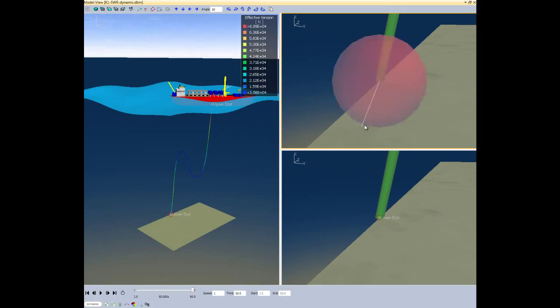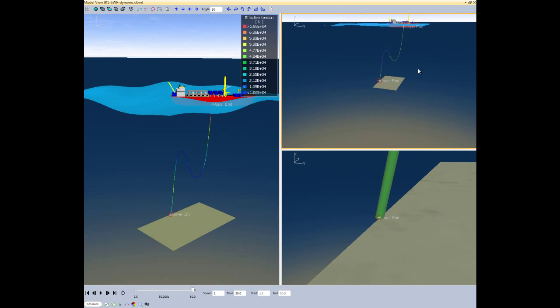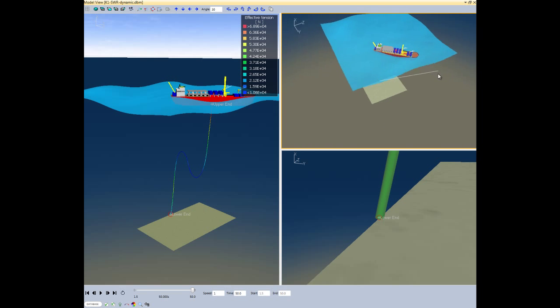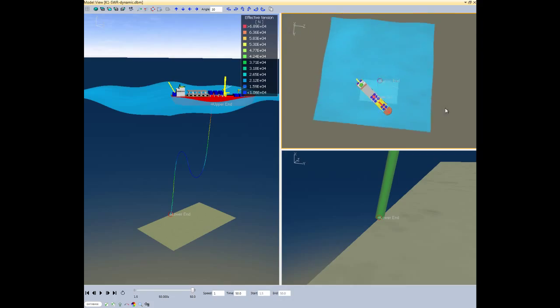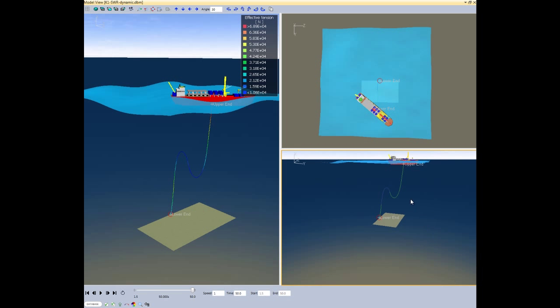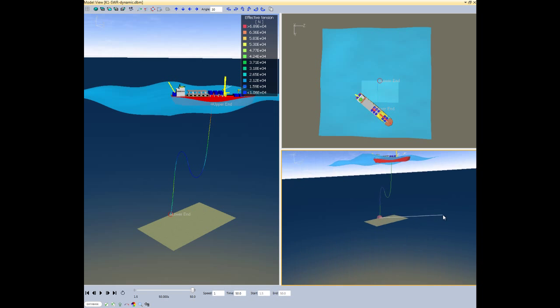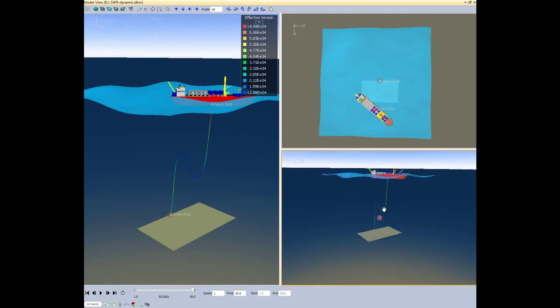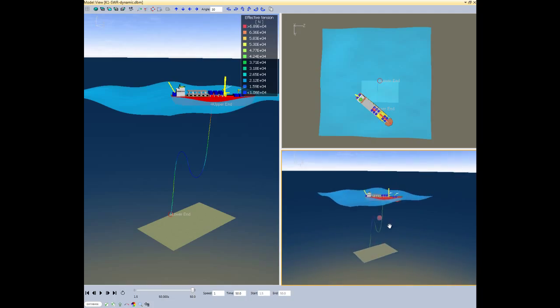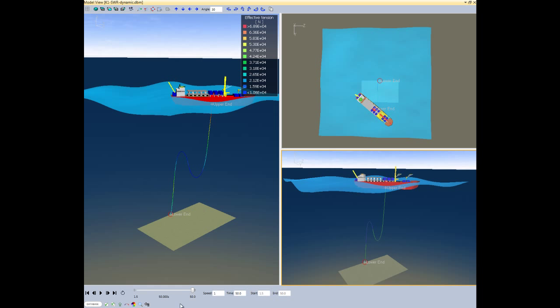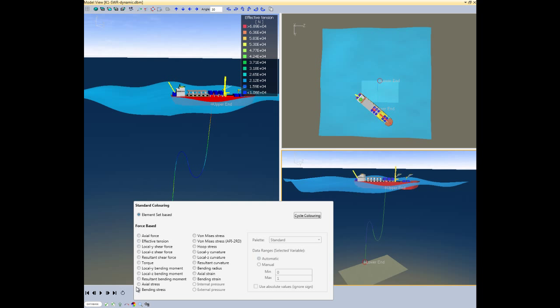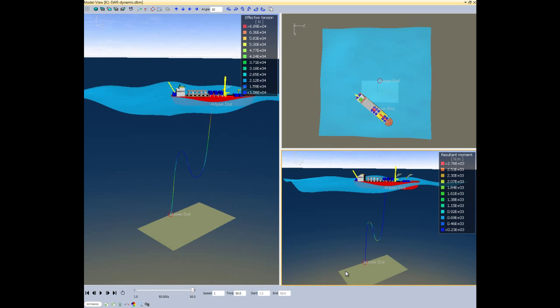You can pan the model using the arrow keys on your keyboard. You can also pan by right-clicking on the screen, holding the mouse button, and then dragging the mouse. During panning or zooming mouse operations, a red circle appears in the center of the screen. This is a useful reference point either for centering an object of interest or rotating the viewpoint around it.